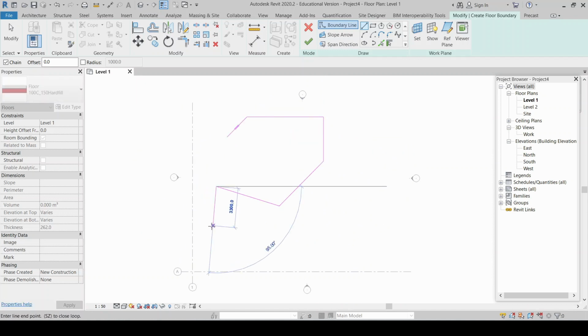As you're clicking around drawing, as I said, it will actually use the objects in the model already to attach to. If you have some objects, when the cursor changes to a square, you're snapping onto the endpoint. So these are snaps. If it's just got a cross and an object underneath turns blue, that means you're attaching to it somewhere. You can be at right angles to those as well. So there's various snaps we can use to generate our lines. But for this example, we'll just draw some random lines.